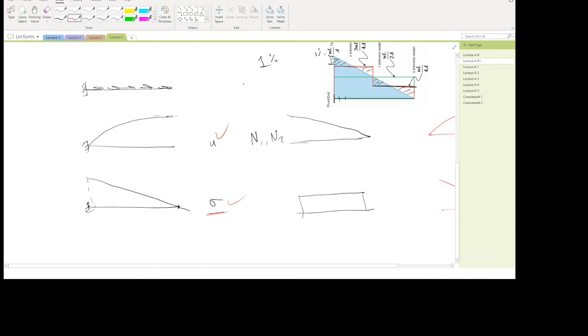When using the finite element we have been working on so far, so this is the linear element we have developed, we know that the shape functions would look like a line, and the derivative of a line is going to be constant. So this element we have in here is going to try and interpolate the parabola using a line. So something like this. And then it's going to try and interpolate the stresses with a constant.